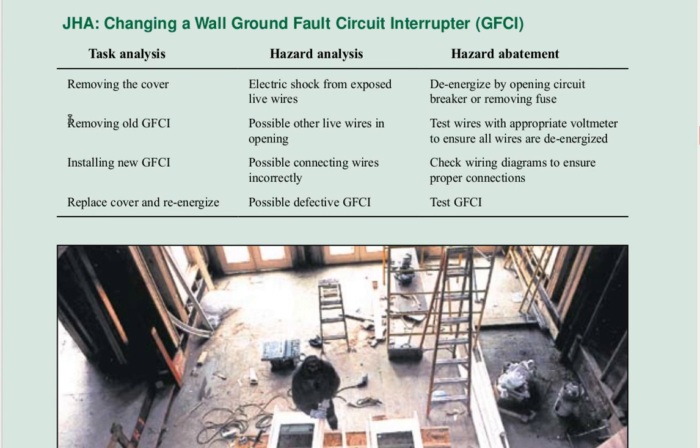Next task you will do, removing the old GFCI. The hazard analysis. In other words, what can go wrong? Possible other live wires are in the opening. Hazard abatement: test wires with an appropriate voltmeter to ensure all wires are de-energized. So you can use a voltmeter or an approved voltage indicator.